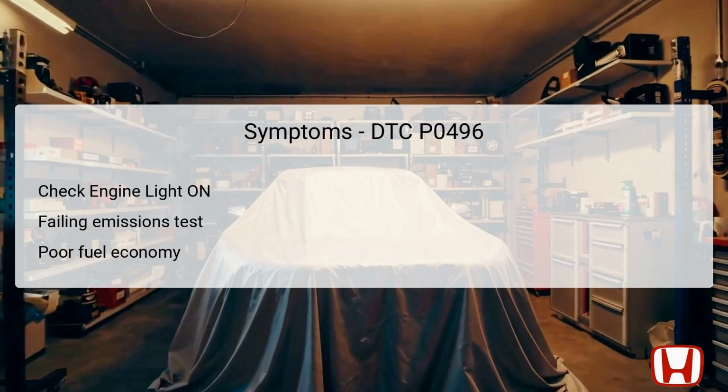The symptoms related to the P0496 code may include an illuminated check engine light, CEL, on the dashboard, which serves as a warning that the EVAP system is experiencing issues. Drivers may also notice a failing emissions test, which can prevent vehicle registration in certain jurisdictions, as the EVAP issue can lead to increased hydrocarbon emissions.